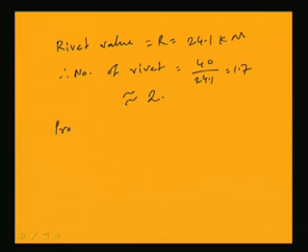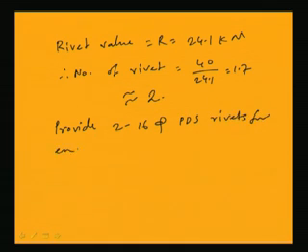That means we can provide 2 numbers of 16 mm diameter power driven shop rivets for the end connection, okay. So, when we make the connections using 16 mm rivets, we will require 2 rivets at each end, okay.